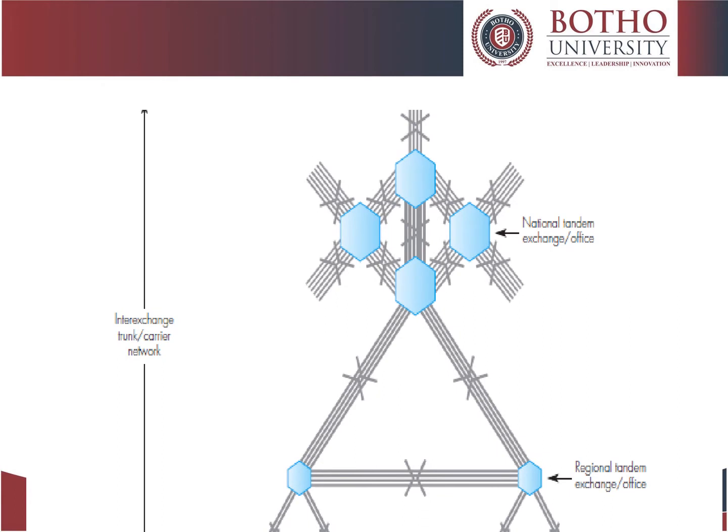These are national networks concerned with the transmission and switching of calls between different regional and national exchanges or offices. In the case of a PSTN, analog transmission is used over each subscriber line, a bandwidth of 200 Hz through to 3.4 kHz. With an ISDN, digital transmission is used over the subscriber line, which is then known as a digital subscriber line, DSL, since all the signals relating to a call are digital. Typical bit rates are 1.5 Mbps, supporting 24 calls, or 2 Mbps supporting 30 calls.